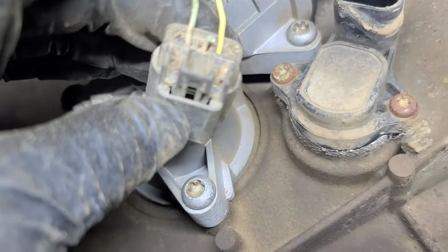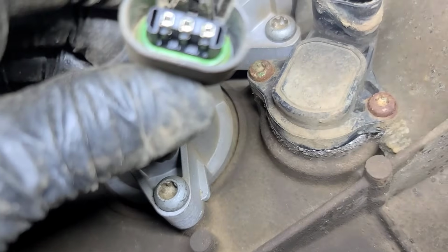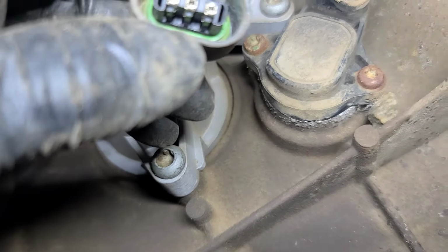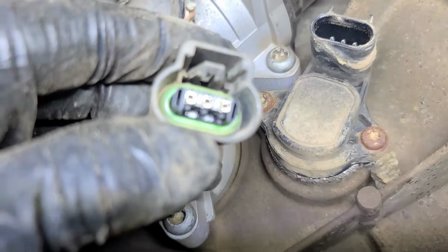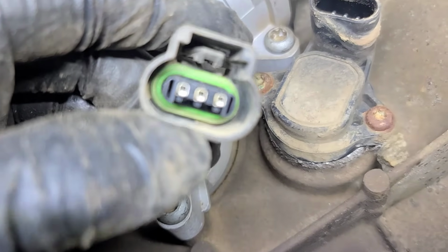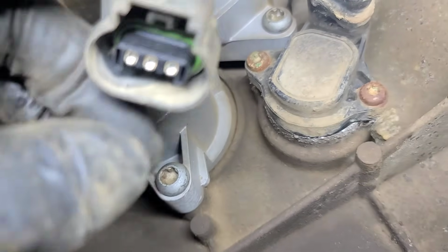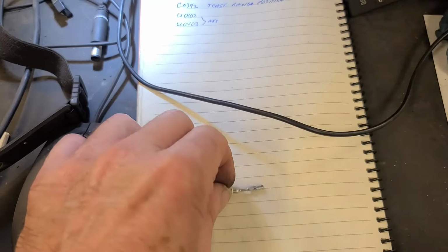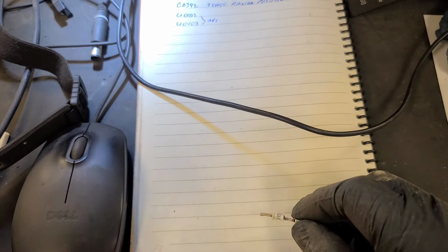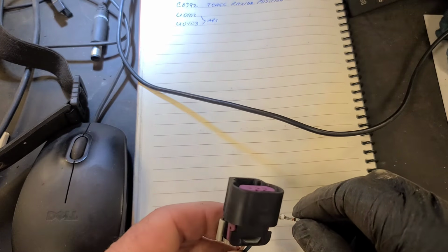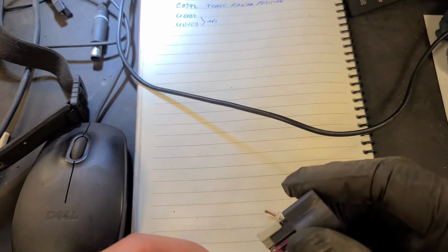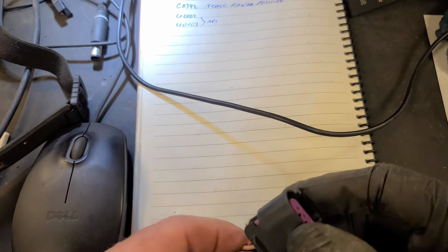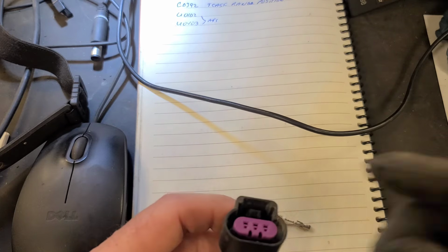So remove the secondary lock, remove the insert in there, and then that middle pin is what we're going to push out. There's a plastic lock there. Push it towards my thumb and then push the pin out. I need a coffee this morning, I'm shaking too much. So there's the terminal, and this is a MAP sensor connector off of an engine job that I did where the used engine came with a partial harness on it. And this actually plugs in.